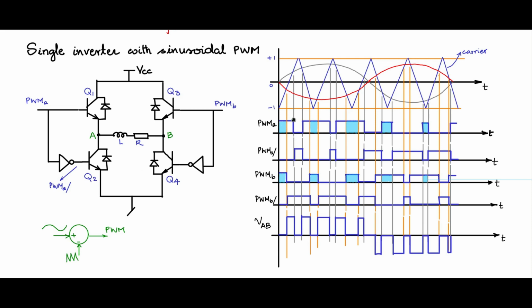That is, we turn off Q1 a bit earlier, and we turn on Q2 a bit later, so that you can fix a period of time called the dead time period, when both Q1 and Q2 are off, that you have ensured Q1 is off and Q2 is still not turned on. So this is a problem that we need to solve.